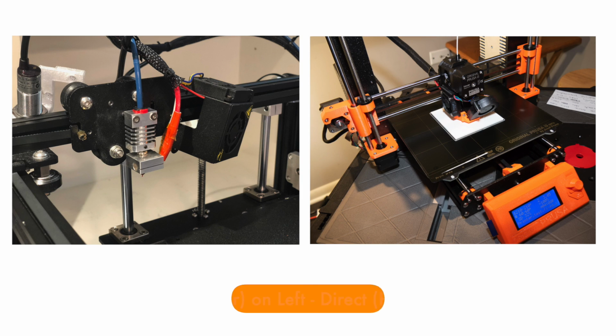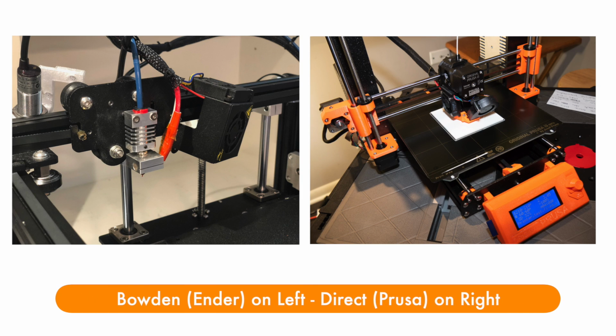However, because the extruder is not mounted right on top of the print head, they can be manufactured more cost effectively because that extruder adds weight. And if you add weight to the print head, you need more sophisticated, more robust mechanics in order to print reliably. So there are advantages and disadvantages. Most often, low-cost printers are Bowden tube printers, and higher-priced printers are often direct extruder printers.